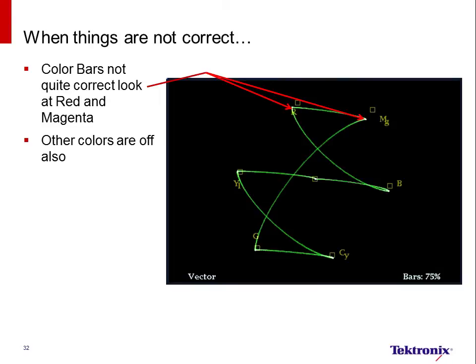In this slide, we're looking at the output of a device that was producing color bars. If you look at the color bar, especially at the top, at the red and the magenta, you can see that the red and magenta are substantial ways away from their target boxes. Without having a device that can either look at HDMI, and especially if it was HDCP'd, you'd actually have no idea that you are producing an incorrect color representation of the original data going in.